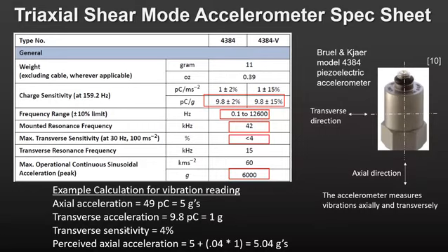This is not a great deal of charge. The only way to measure it is to feed the signal to a charge amplifier and read the voltage output. The sensor can measure acceleration up to 6,000 Gs, far higher than the capacitive or piezoresistive types. The accelerometer will pick up a small amount of transverse vibrations when measuring vibration in its axial direction.